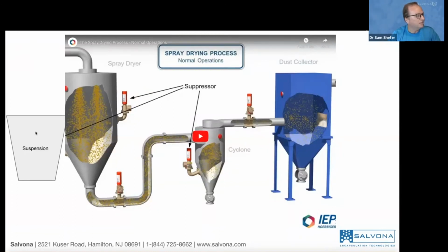What you see here is the spray dryer. This is the major spray dryer unit. Then you see there are pipes connecting to a cyclone. This structure is called the cyclone. Particles are supposed to fall down into the connector. Here we combine everything that falls down. However, there are tiny particles, and these can continue to flow into the dust collector. Typically, we consider this garbage.